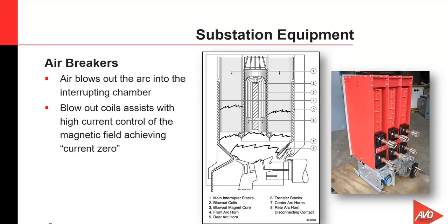Those contacts are designed to prolong the life of the main contacts. With this air type of breaker, we've got a real good demonstration, a good cutout of an arc chute, and how the arc chute works. The arc chute is designed to accept that arc when the breaker opens up, and there's going to be a small puff of air.